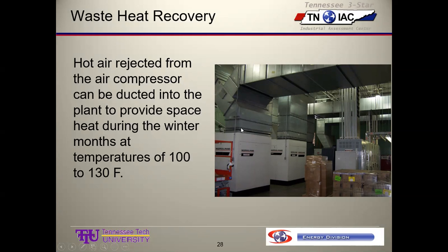Or if it's air conditioned, you sure don't want to air condition that heat away. But in the wintertime when it's cold, you can throw the dampers the other way and throw it out through these ducts, and it distributes it out and blows it into the facility. And this is probably the best distribution system I've ever seen.